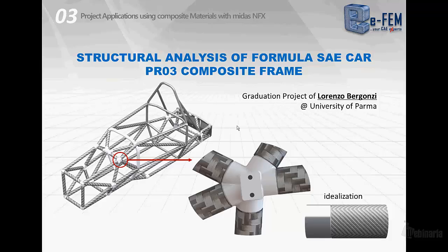We need to specify that each pipe has been linked to the others by means of adhesive bonded joints. These joints have been idealized as shown in the picture, and the study starts from the generic study of the global model of the frame and ends with the evaluation of the worst bonded joint, by means of a sub-model of the bonded joint itself.